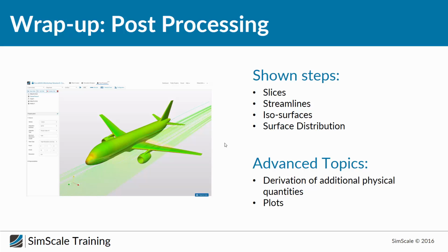I showed you how to create slices, how to create streamlines, isosurfaces, and to visualize surface distribution of pressure or Y+. And there's some additional stuff you can do with our online post-processor, like creating plots or using the calculator to derive your own physical quantities. But this is something you can really learn by playing and doing.